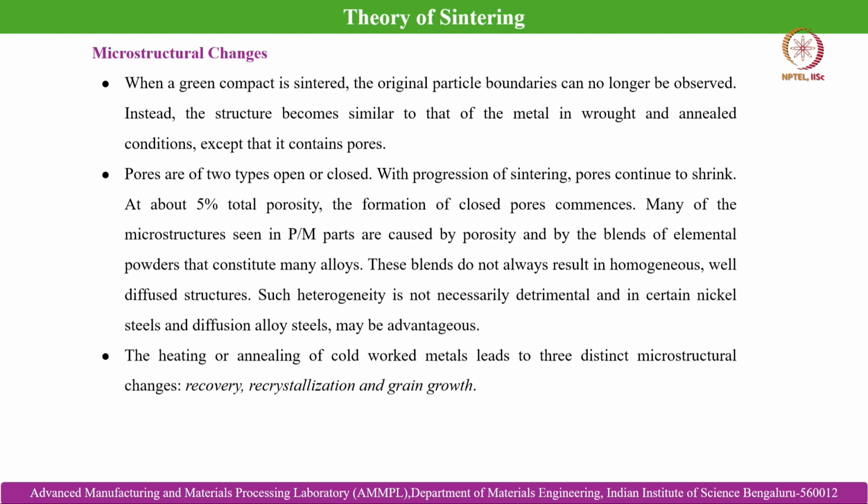Many of the microstructures seen in PM parts are caused by porosity and by the blends of elemental powders that constitute many alloys. These blends do not always result in homogeneous, well diffused structures. Such heterogeneity is not necessarily detrimental, and in certain nickel steels and diffusion alloy steels may be advantageous. That is why the microstructure can be bimodal in the case of powder alloying, where in situ alloying takes place.